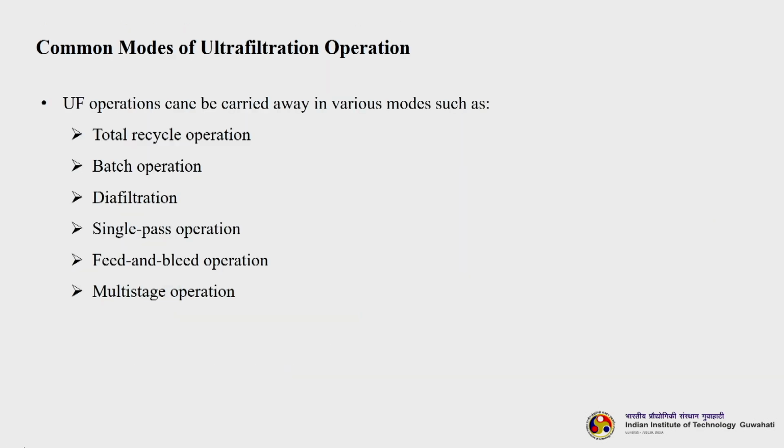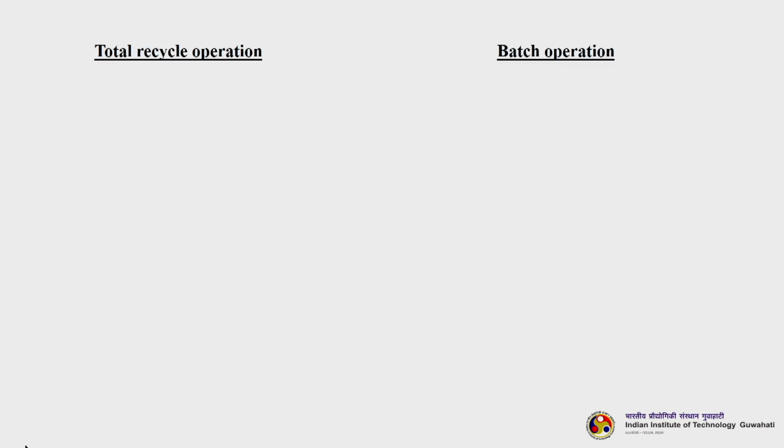Now, let us try to understand one of the most important things, that is the common modes of ultrafiltration operation. There are various modes. Most commonly these are the modes of operation: total recycle operation, batch operation, diafiltration, single pass operation, feed and bleed operation, and multi-stage operation. I will try to draw sketches. Let us see how the total recycle operation looks.